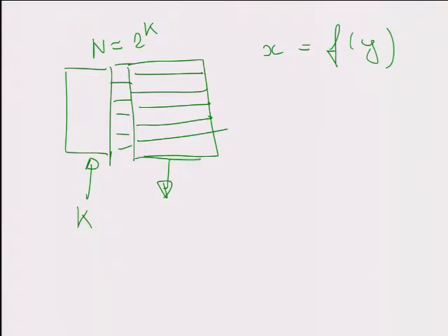And the width of the word that comes out is going to be equal to M. This is like 16-bit words or whatever I've stored in my memory. So in a typical memory read operation, you apply an address, you get a data word out.